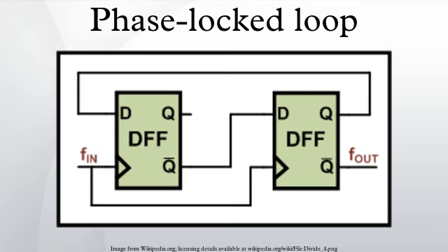One way of eliminating this delay is to include a deskew PLL on the receive side, so that the clock at each data flip-flop is phase-matched to the received clock. In that type of application, a special form of a PLL called a delay lock loop is frequently used.